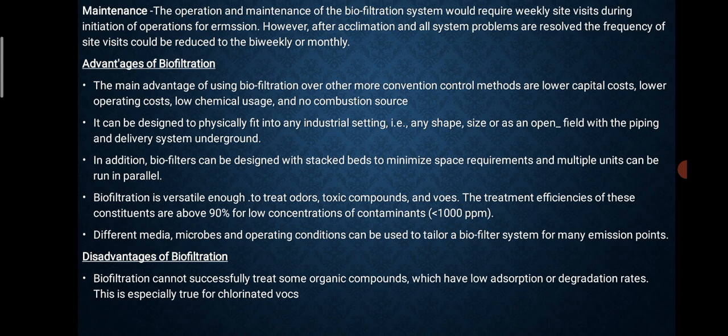Then maintenance. The operation and maintenance of the biofiltration system would require weekly site visits during initiation of operation for emission. However, after acclimation and all system problems are resolved, the frequency of site visits could be reduced to monthly.